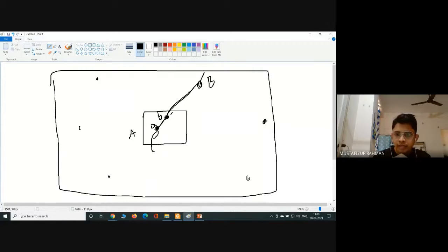Then here also we have another point. So here also we will sight first. We will have a ranging rod, which is called a signal. With the help of the ranging rod, we will mark the direction first, and then we will measure the distance, and then suitably we will draw it here. If it is C point, here we will have our C point. Similarly, in all other directions, we will draw our lines. And from there, if we have to take data from these points, we can take this data.